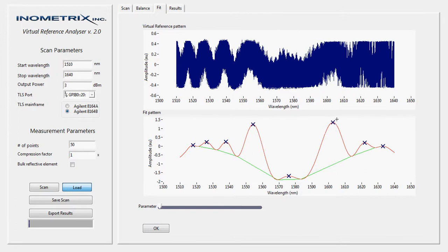So we're going to choose two peaks on both sides of the center and take the average. That's going to give us a plot where we know the center. We know the group delay, and we just need the wavelength where that group delay is equal to that of the device. So we can plot group delay versus wavelength by just changing the length of our virtual cavity. Now we want to make the fit. You want to fit to this pattern very well.